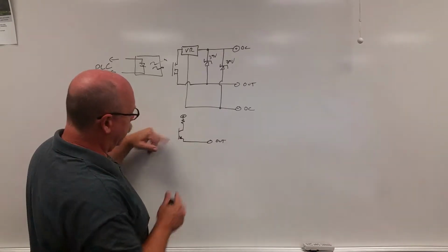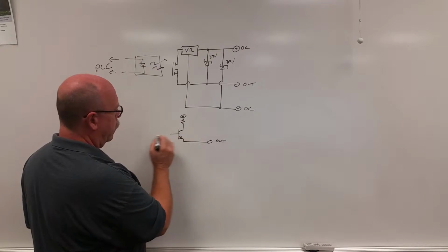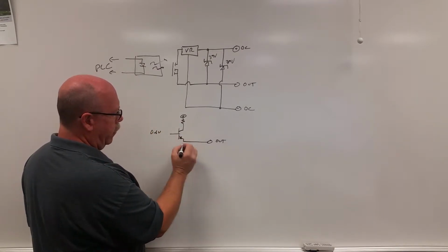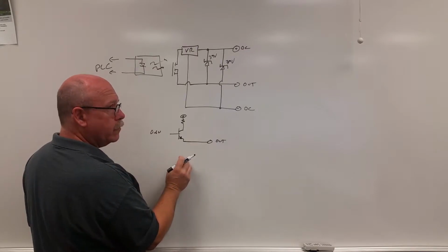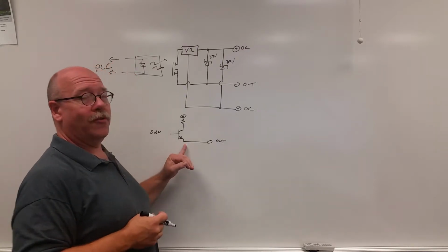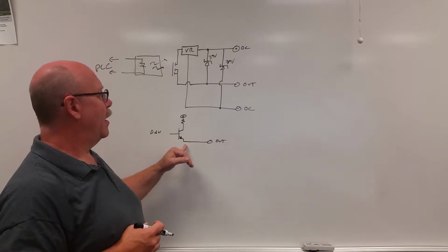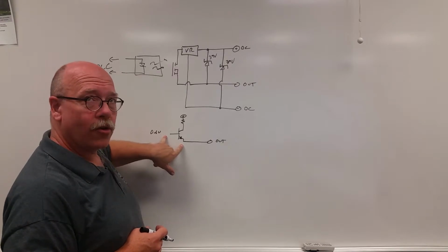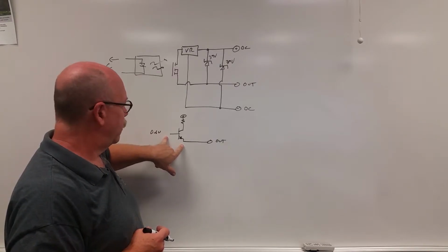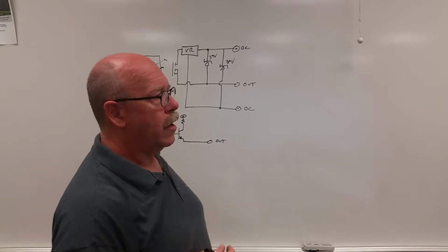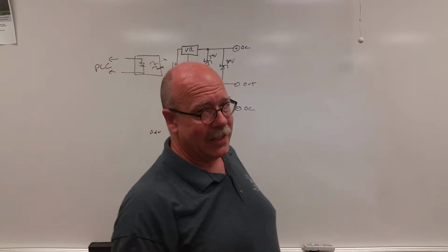At this point, it requires a voltage that is 0.6 of a volt higher than the emitter. Typically, you cannot source as much voltage out as you're putting into the device because of the limitation across the base-emitter junction. Also, the transistor is limited internally by its beta, or its DC gain.